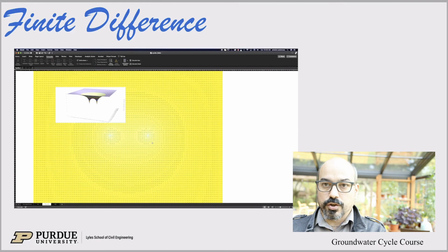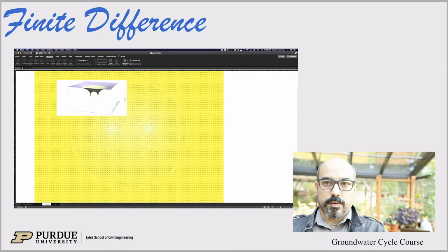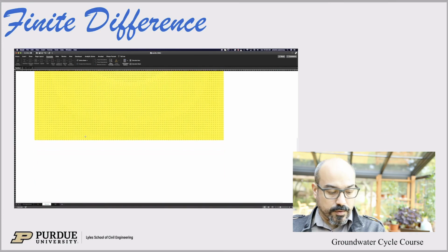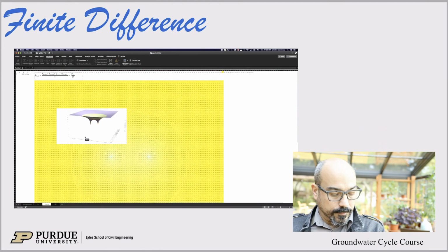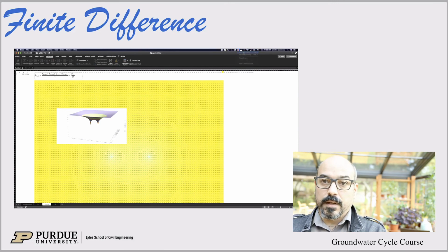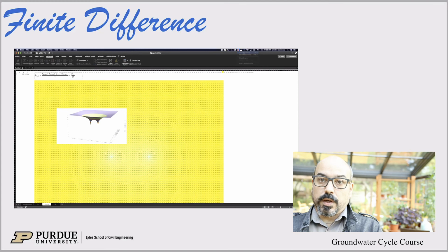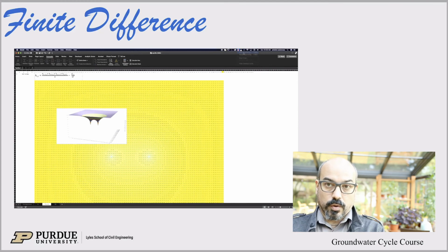Here is a larger domain where you can clearly see the circular impact of the wells, almost like the radius of influence on that bigger circle. You can really see the influence of the well on the aquifer, that radial, circular influence. Again, two wells, and you can see the 3D version up top here. But you can have domains that are basically arbitrarily large. Okay, that was just a quick demonstration of how to use finite difference methods to solve flow equations